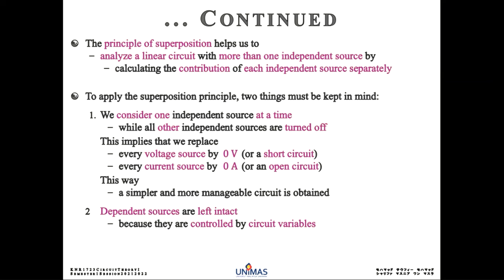And one more thing, okay, you cannot combine whatever voltage or whatever resistor that you are going to find the current or voltage, because if you combine, your resistor, your branch will be lost and you don't know what is the value that you want to calculate. So remember, don't touch the resistor in the branch that we want to calculate.